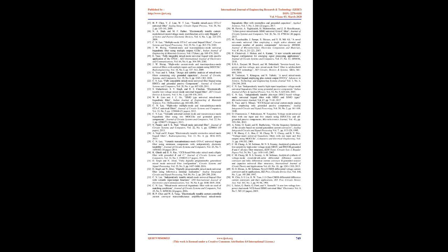Furthermore, the proposed general mixed-mode circuit still enjoys many main advantages, using 2 grounded capacitors attractive for integration, no inverting or non-inverting amplifiers for special input signals, no component value constraints except the CM/TIM all-pass responses, high output impedance, and low active and passive sensitivities. HSPICE simulations with TSMC 0.25μm process confirm the theoretical predictions.